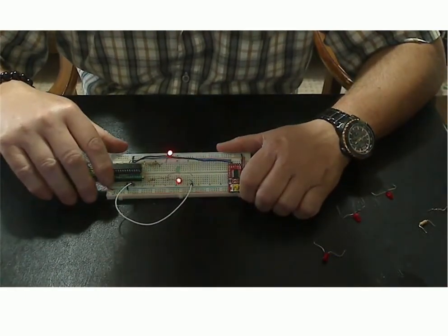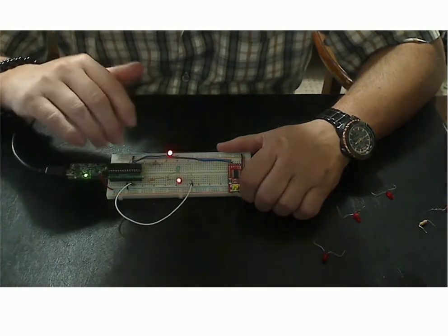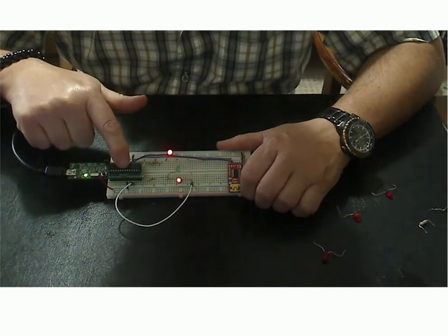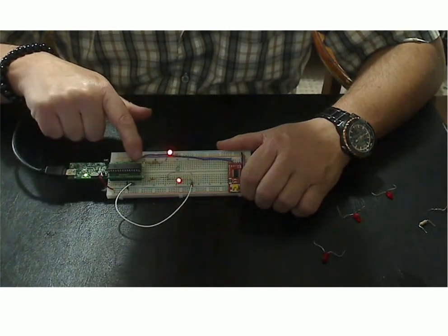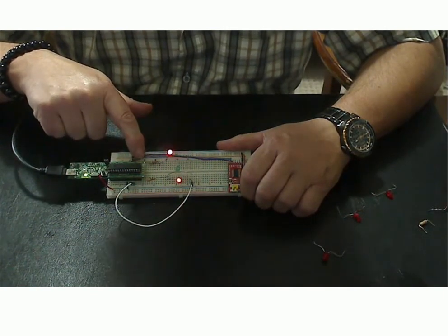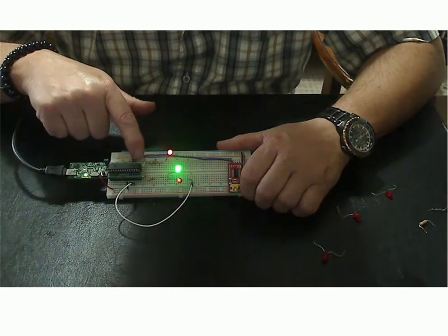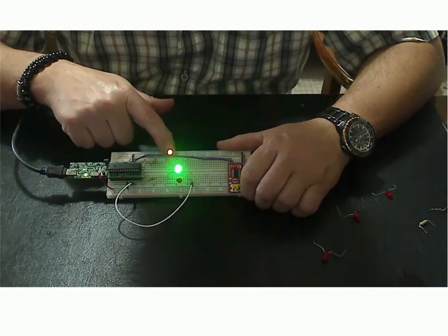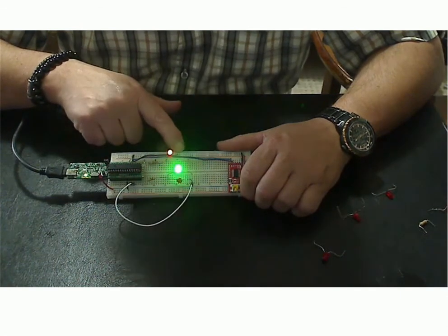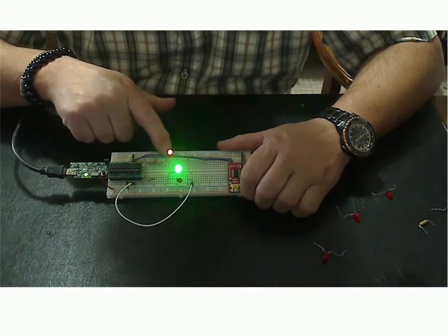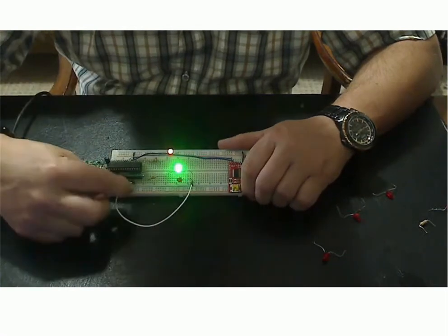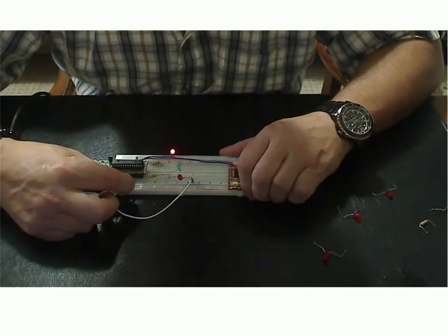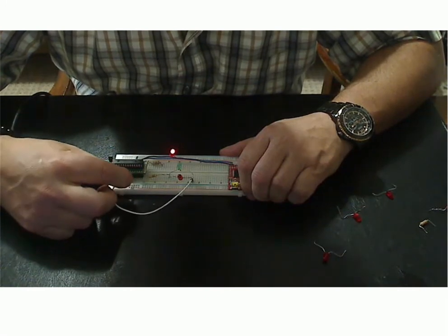In the time that I paused this, I've put in the circuit. There's a little program here, and one of the things it does is take pin 15 and turn it high. I've connected a resistor and an LED to ground, so of course the LED lights up. Over here, I'm using two pins, pin 11 and pin 14.